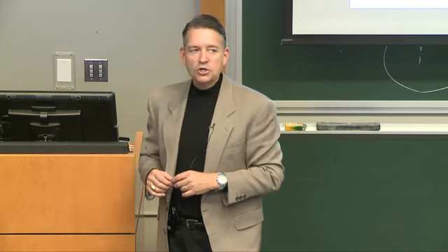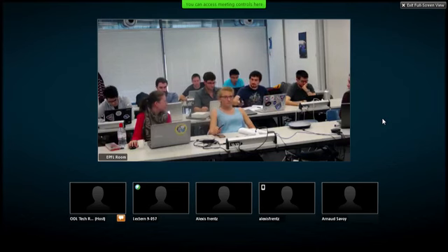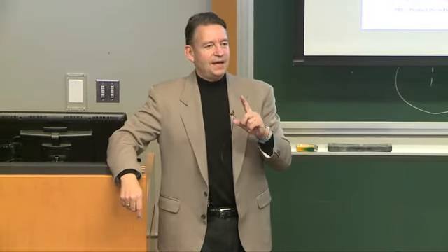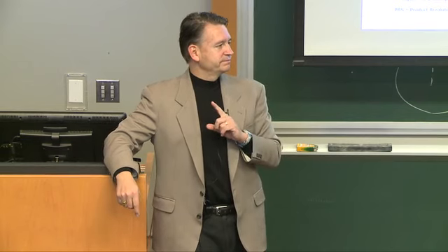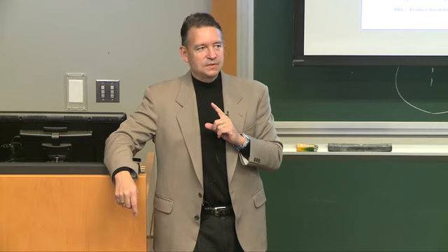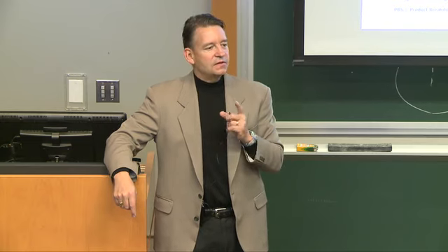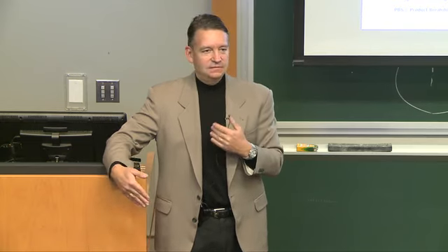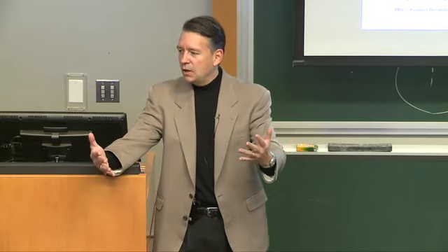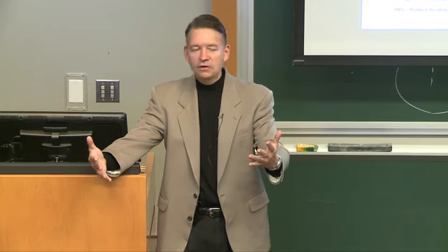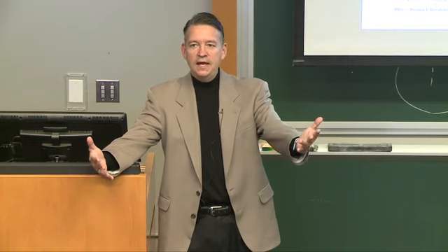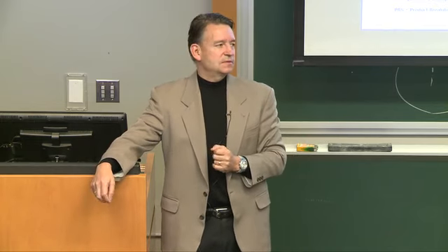Commercial off the shelf. So you have to decide in the detailed design, are you going to pick components from a catalog, or are you going to custom design these components? One of the things I always ask at the CDR is, you present your design, what fraction of your parts at the lowest level are COTS, and what fraction did you custom design?